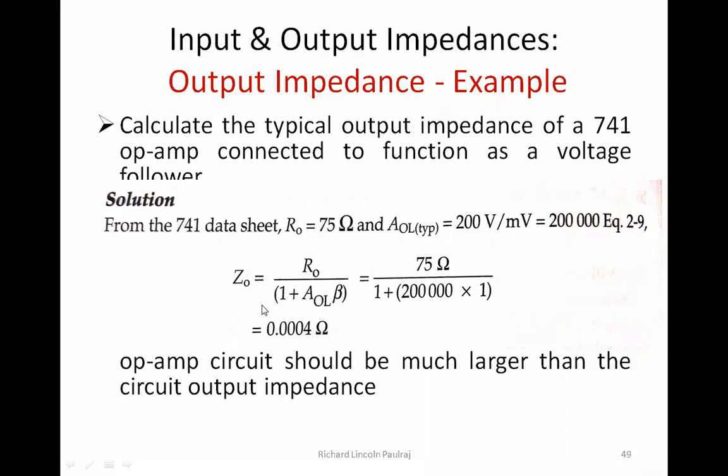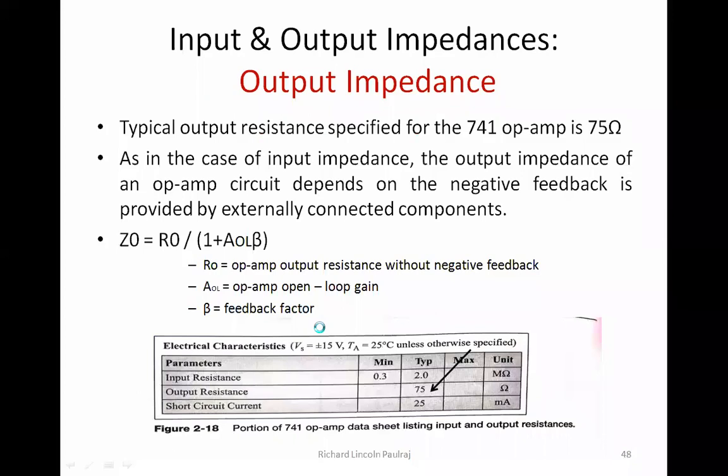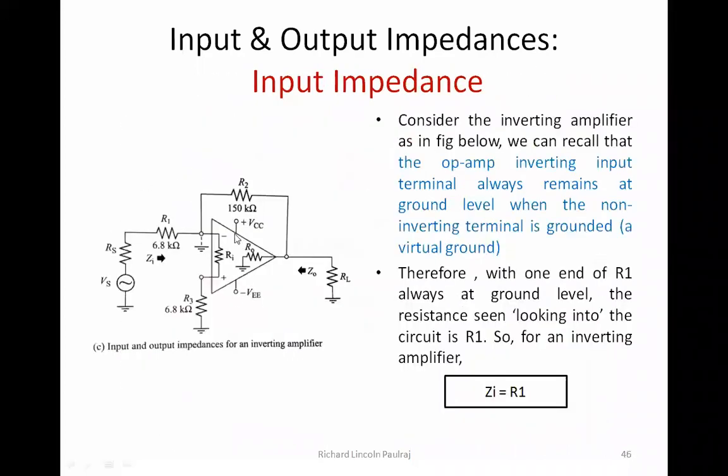I've seen instances where students tend to get confused with the type of formulas, with the inverting and non-inverting configuration. So you have to be careful in looking at the circuit, which has plus and minus terminals. Because of these terminals, you may tend to use another formula, and then whatever time you have spent in solving the problem goes wrong. So attention to detail is very much needed when you're looking at the circuit, and try to analyze what kind of formula you're going to use.